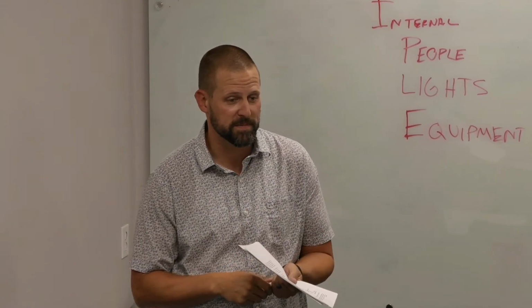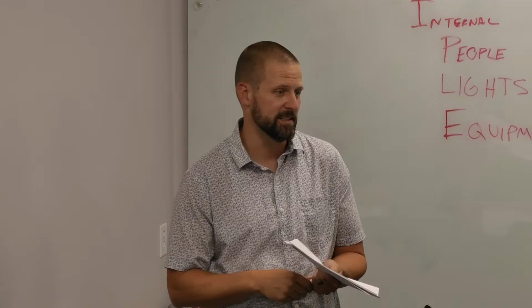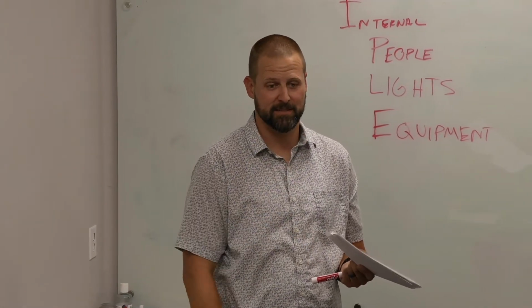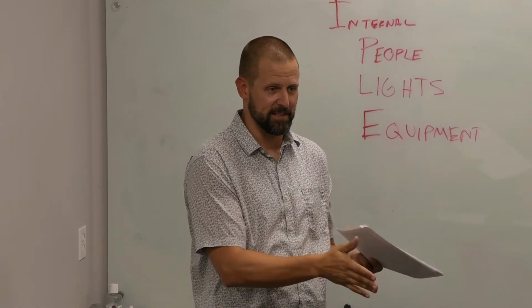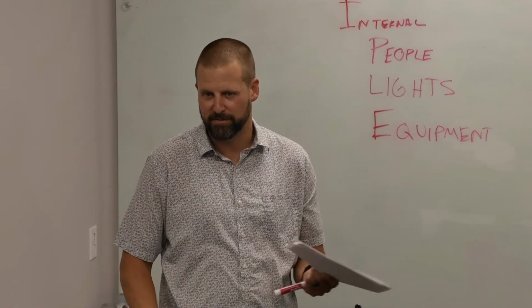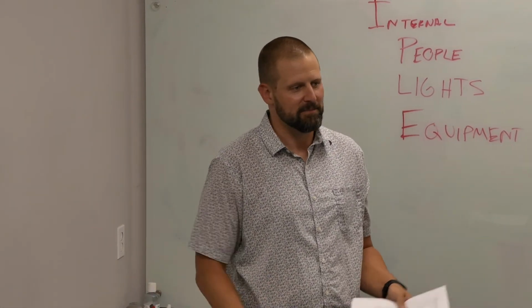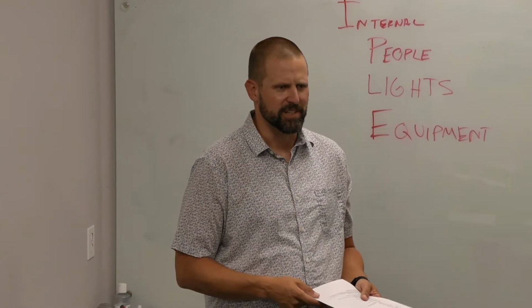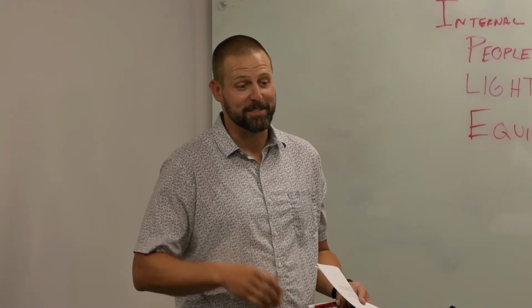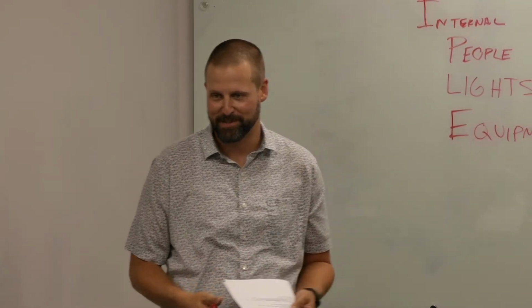So electrical rooms are rooms where we're typically going to add up the transformers and use something to come up with a heat load. Rule of thumb is usually 3% of the kVA. It's going to give you about the heat load for that. New transformers are much more efficient than that, but it varies. So you should hem and haw about it for a while, or ask me. Also, you should make your engineer come up with that, so you don't have to, right? But this is a good way to check this type of thing. So electrical rooms have a lot of those. Transformers can be in the space too.